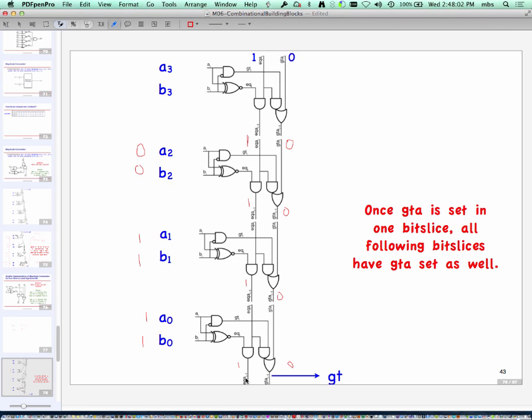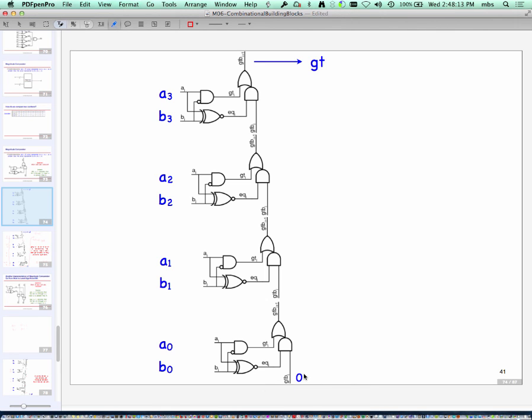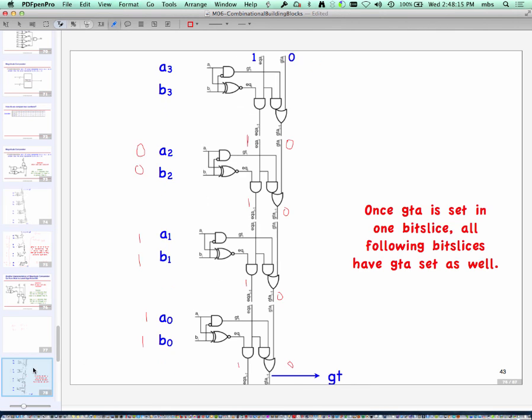For every design, you have to think of what the boundary condition is. That's really going to be specific to the logic. In our previous design, which we had seen here, our boundary condition was 0, right? So it will depend on design to design. For example, oftentimes we are given adders, and we'll see later on the next slide set, and there's a carry in at bit 0. We usually tie it to 0 because there was nothing coming in. So the carry in to the units position is 0.